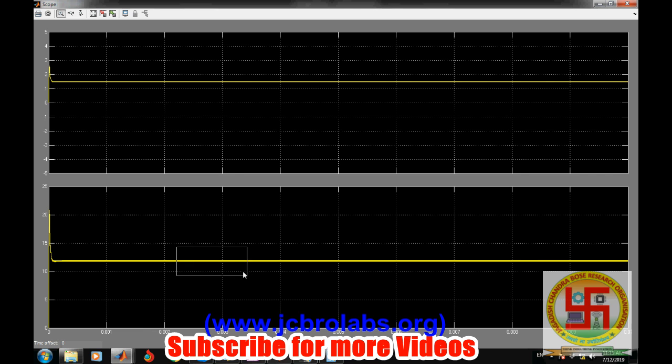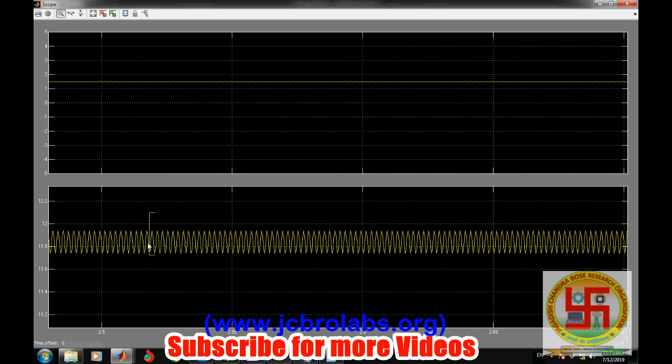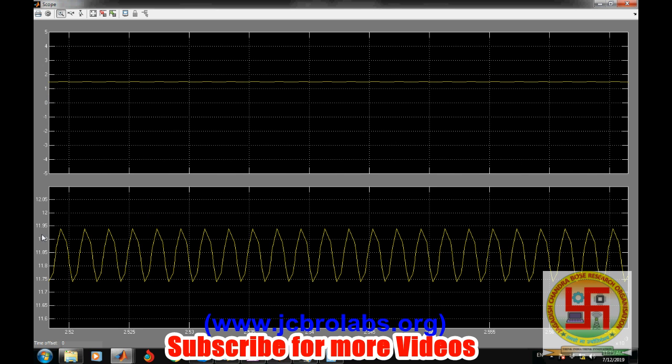Now if we look at the ripples appearing here, the ripples are within the range of 200 millivolt. Look, it is going up to 11.95, and here it is near about 11.75. So ripples are within the limit of 200 millivolt. That's why we said that is the minimum value of C which is required for that amount of ripple.